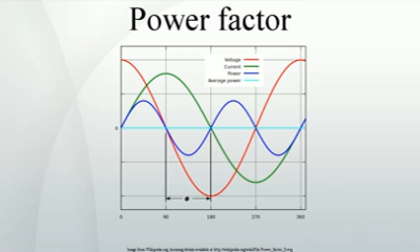In a delta-Y transformer, these harmonics can result in circulating currents in the delta windings and result in greater resistive heating. In a Y configuration of a transformer, triplen harmonics will not create these currents, but they will result in a non-zero current in the neutral wire. This could overload the neutral wire in some cases and create error in kilowatt-hour metering systems and billing revenue.